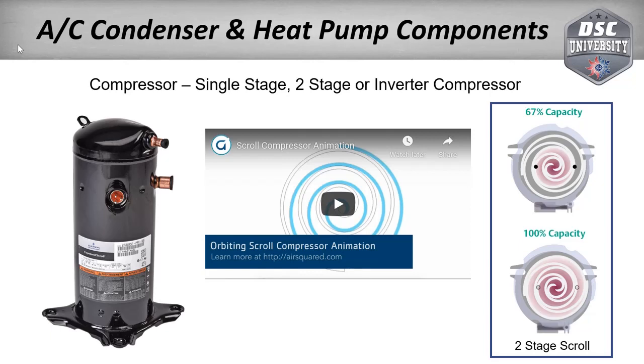They have a couple little holes drilled in there, and when those holes are open, it means that scroll is not completely full of refrigerant. It's only pumping at part capacity, which means the system's only operating at 67% capacity. When those holes are closed, it goes back to operating at 100% capacity. So that gives us the ability for that unit to run at 67% when we don't have a lot of demand, and then when we have a higher demand, it can shift up to second stage and give us 100% capacity.